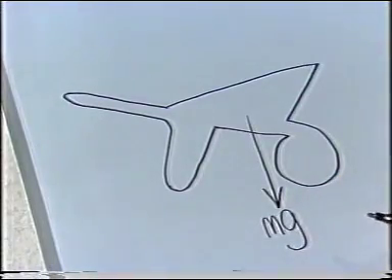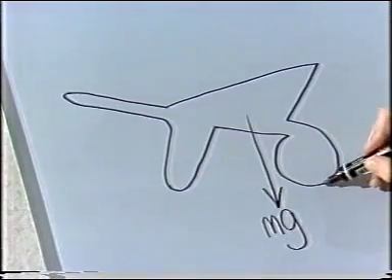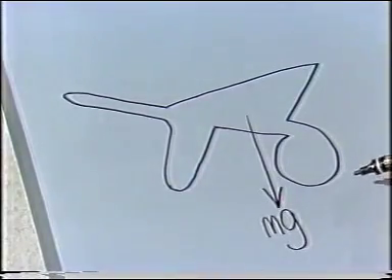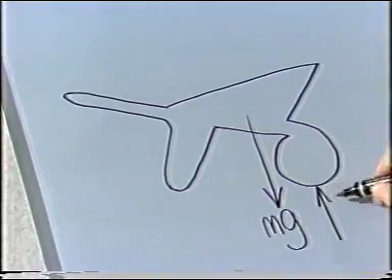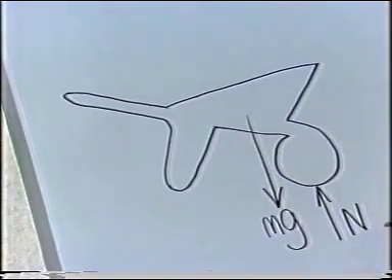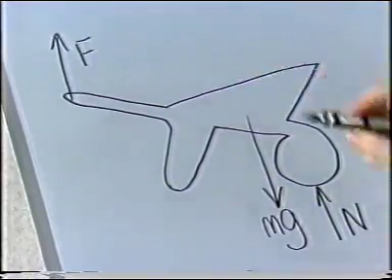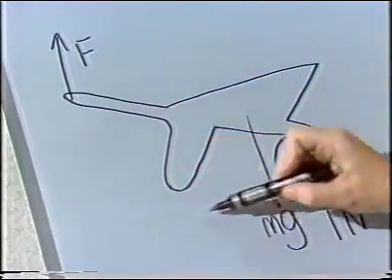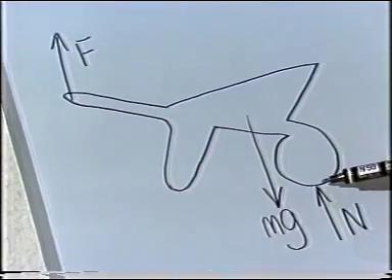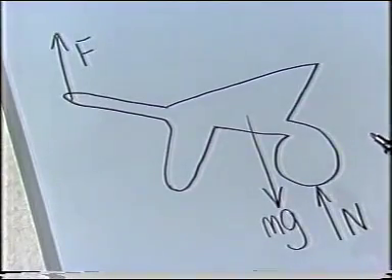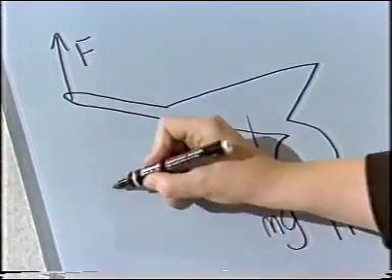There's a reaction force acting at the point of contact between the wheel and the floor. There's no possibility of slipping, so the reaction acts in a vertically upwards direction. I'll call that force N. Finally, there's the force that John exerts. I know that it acts vertically, so I'll represent its magnitude by F. It acts through a point which is B from the front contact point. Next, I select axes. I do this by looking at the forces acting on my free body and aligning my axes with as many forces as possible. In this case, it's a pretty clear choice.